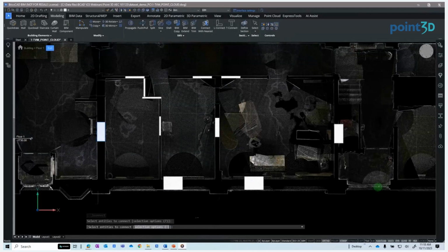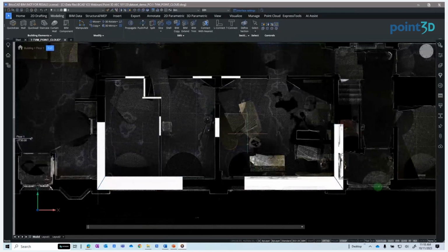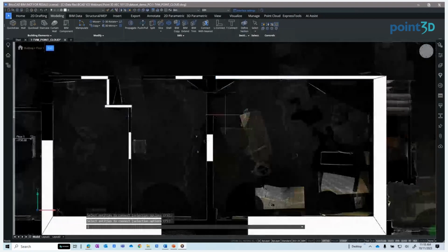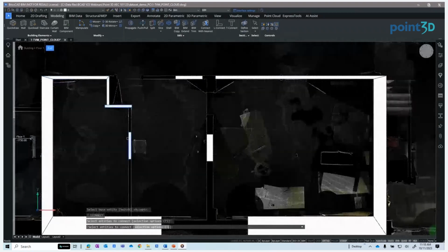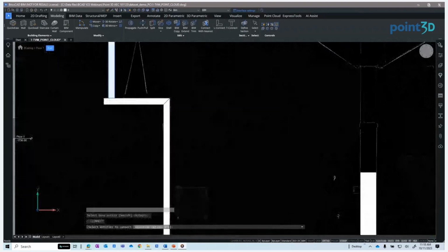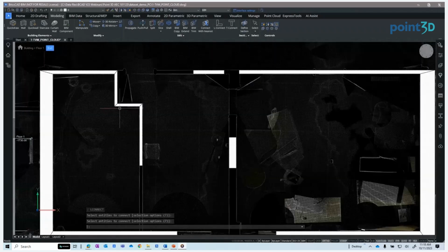Now we only need to place a small part of the wall, as our automatic cleanup tools are going to be used to clean up and connect the walls. Those tools are the L-Connect and BIM Extend. So with L-Connect, you select 2 walls and connect them, and it's that easy. Now, there are options to toggle between how those walls are connected. There are a couple of different butted connections, L's and T's, or mitered connection. And L-Connect works with walls of similar or different thickness. You can see there a really thick wall and not so thick wall.